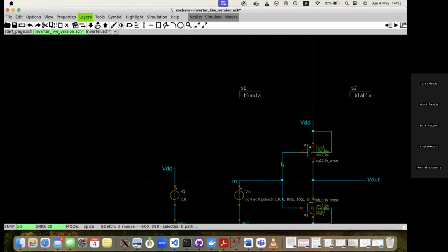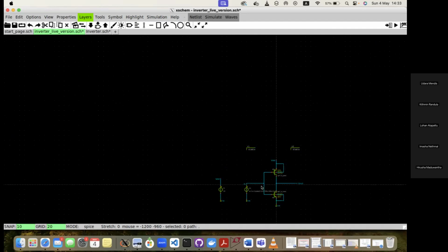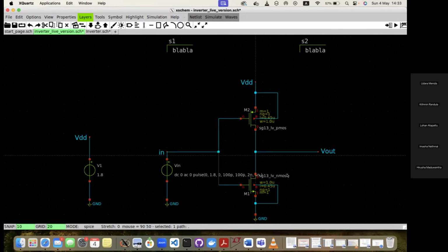In MOSFET design, the most common equation is half times mu n Cox, electron mobility times unit capacitance, times W over L, times VGS minus VTH, squared. That is the equation you use every time. Sorry about my drawings. VGS means gate-source voltage, minus VTH. This will be the equation for NMOS, and similar for the PMOS. So this will be the equation of the drain current.